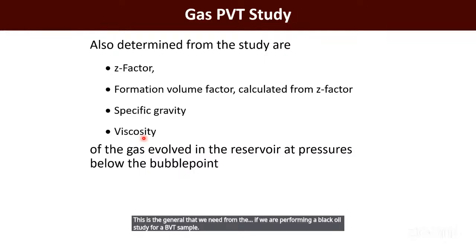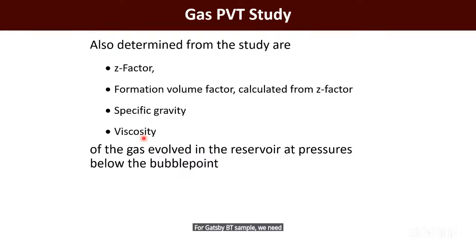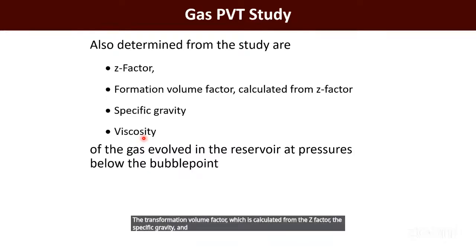This is the general requirement if we are performing a black oil study for a PVT sample. For a gas PVT sample, we need to have the Z factor, the gas formation volume factor, which is calculated from the Z factor, the specific gravity, and the viscosity.